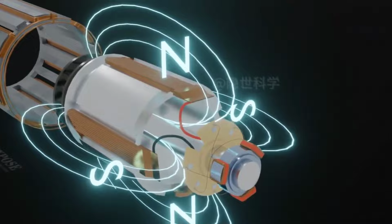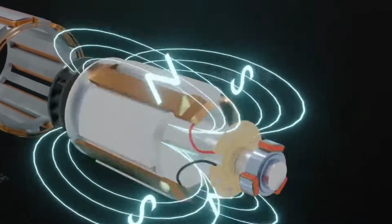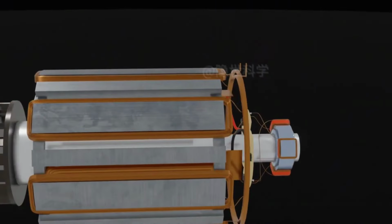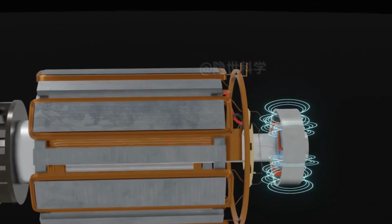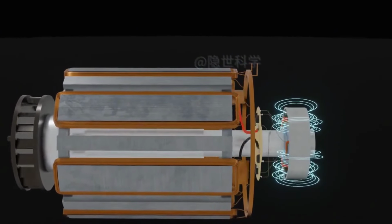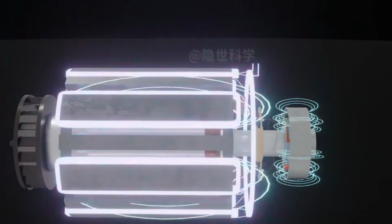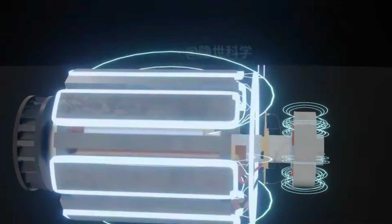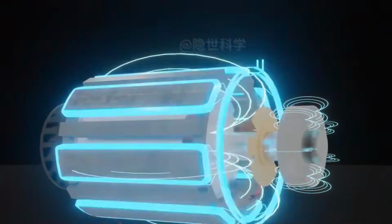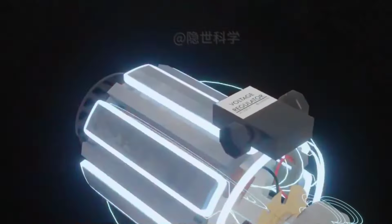Since the excitation system also rotates together, this does not require the use of brushes, so it is called a brushless system. When the generator rotor rotates, magnetic field cutting occurs in the PMG. The generated current is transmitted to the main rotor. When the main rotor is supplied with current, a magnetic field is formed, and a larger-scale magnetic field cutting occurs. Since the magnetic poles on the rotor are alternating, the direction of the current induction also alternates, which will produce alternating current sent to the voltage regulator for processing to meet demand.